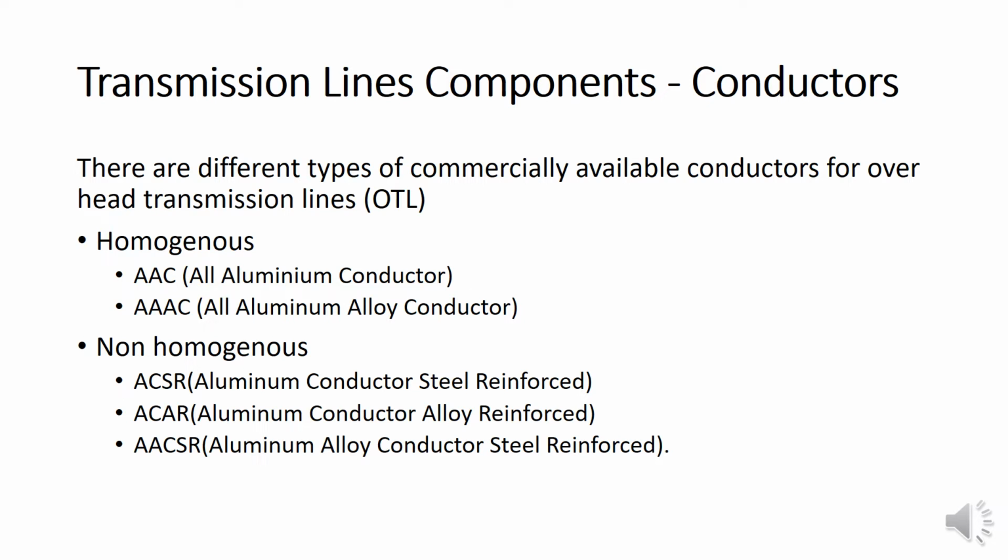As an example, if we just have an aluminum conductor, the strength of that aluminum conductor will be very much less, because aluminum is not good in high tensions. But steel is very good in high tensions. That means it can hold some tension, and it can hold the conductor also. Conductor means the current carrying one.